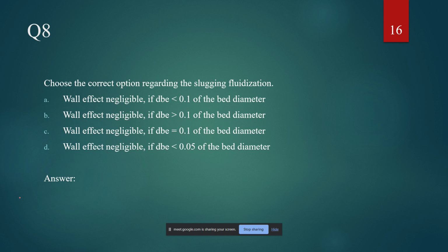In general, there are three types of slugs that are formed inside a fluidized bed. The first one is round nose slugs. Here, it is round shaped and it is frequently observed in Geldart A or Geldart B. All these you would have listened when you have seen the lecture videos. This is just for a quick recap.